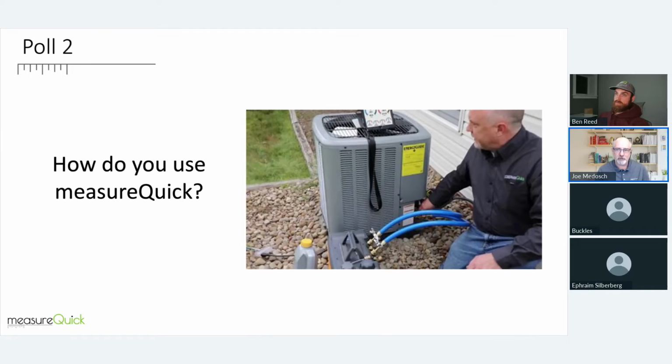That's what determines that. It should never be below the outdoor temperature, so it's usually above it. If you're too close to that, then that's one of the conditions that shows up. Some people don't understand how we define approach, but that's really the condition: the liquid line compared to the outdoor temperature.